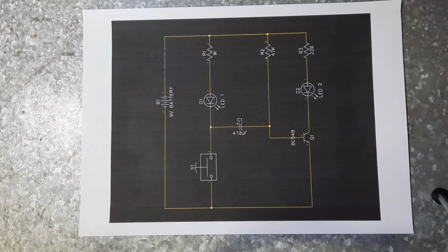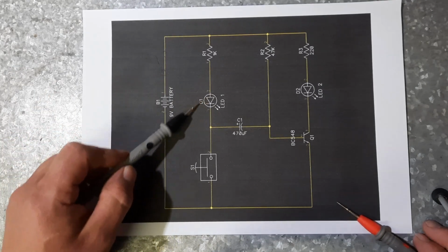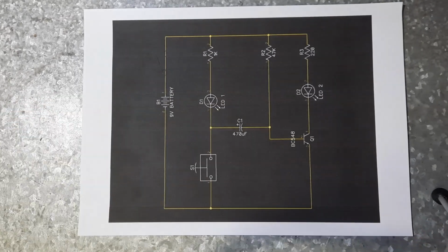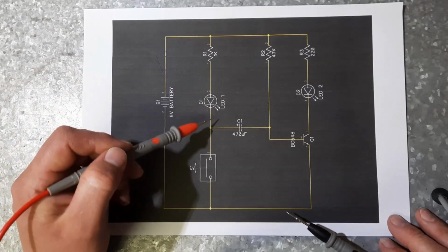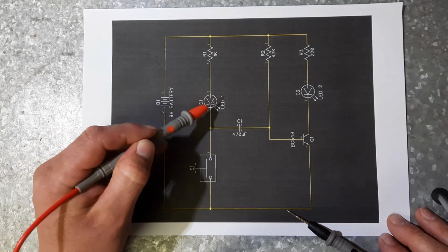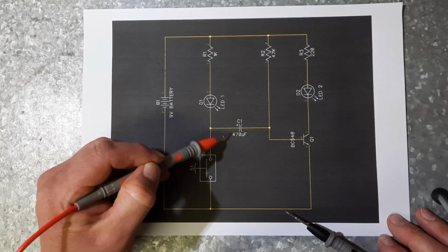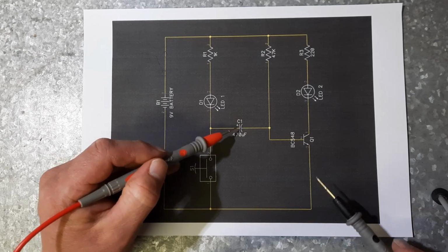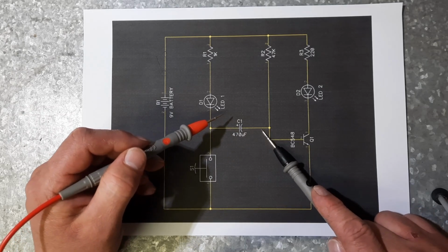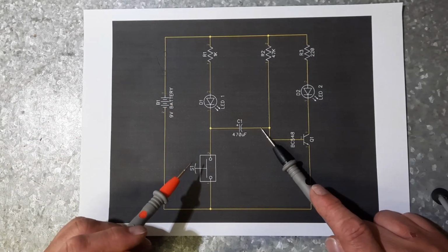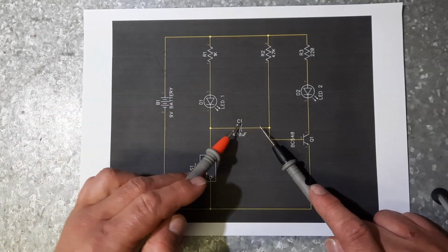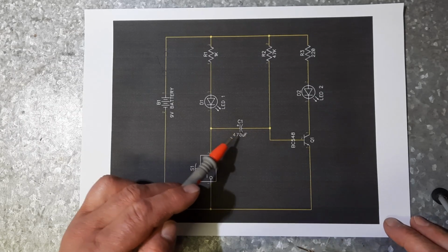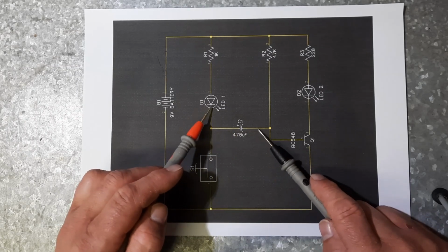What happens now starts to get a little bit tricky because we have a diode here. As this capacitor starts filling up, it'll fill through here. Without this diode here, this capacitor would fill to 8.3 volts. Why not 9? Because the negative plate is already at 0.7 of a volt. So it can only fill so far. It's only going to fill to 8.3 volts without this LED here.